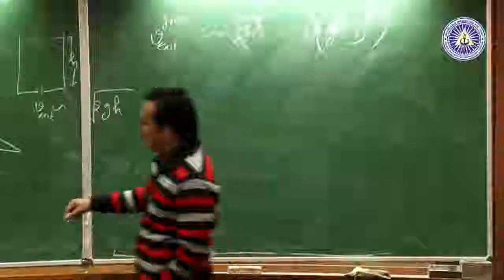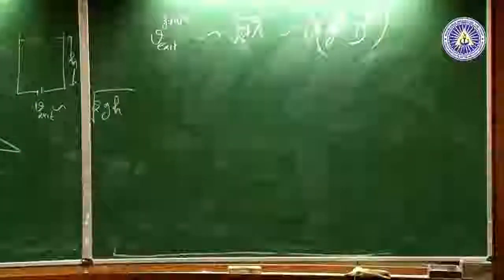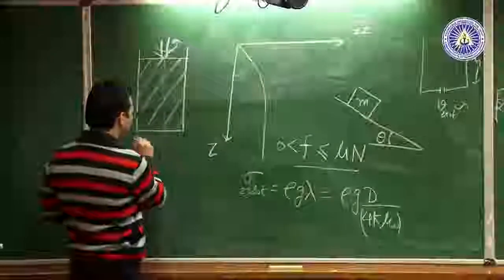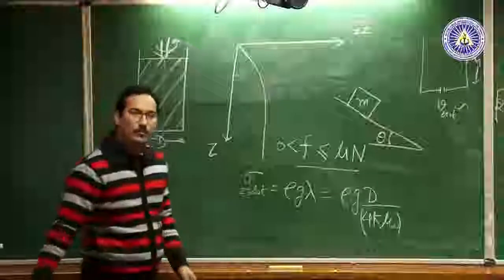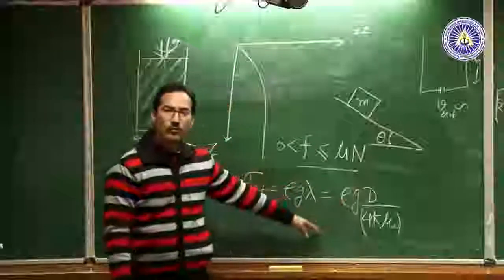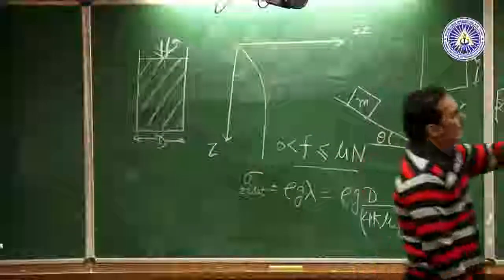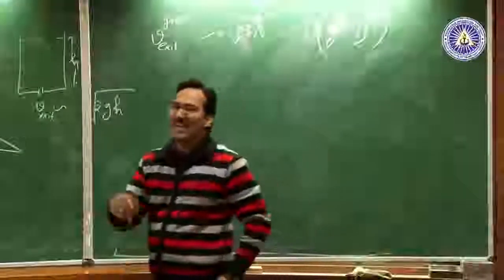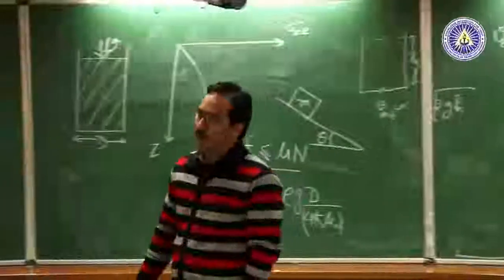So lambda is your screening length or characteristic length, which depends on the diameter of the container. Yes, assuming that friction is fully mobilized. And so if you try to make that connection, you will assume that this is what makes your flow rate independent of the head.